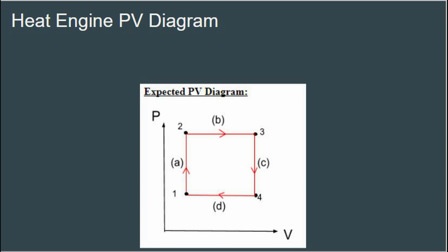The change from state 2 to state 3 is isobaric expansion. Once the pressure under the piston is equal to the calculated maximum, P2, the piston will remain at that pressure and rise to the top of the piston tube. At that point, it has reached its maximum volume, which is found with respect to the temperature of the hot reservoir using the ideal gas law to solve for V2.